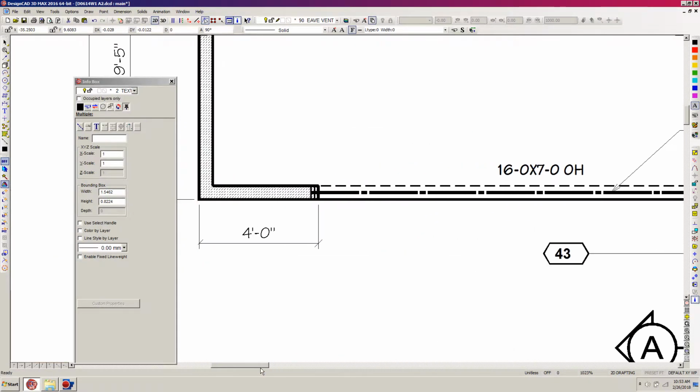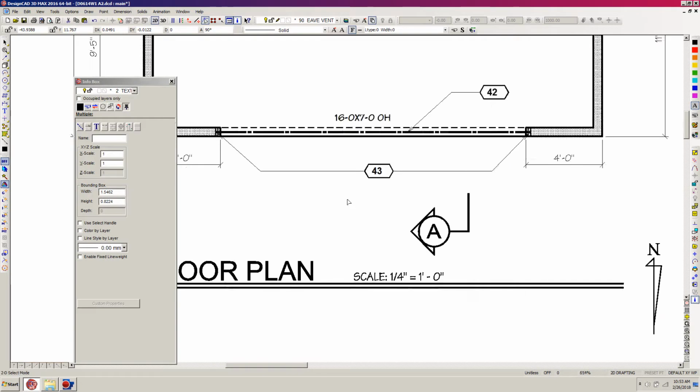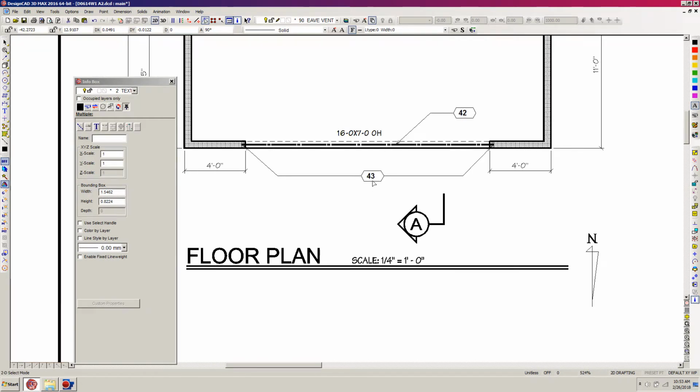I'm going to scroll over and do the same thing on the other side. Again, my arrow command, the greater than, or Shift period, same thing. Right click to the pointy part of my sheet note box, hit H for orthogonal mode, keep it nice and straight, come out a ways, set a point with my left mouse button, H to go out of orthogonal mode, and come over here and hit K at the center of those two trimmers. And then hit my scroll button, and there's my arrow going there. So now I have my arrows indicating both of my double trimmers for the garage door header.